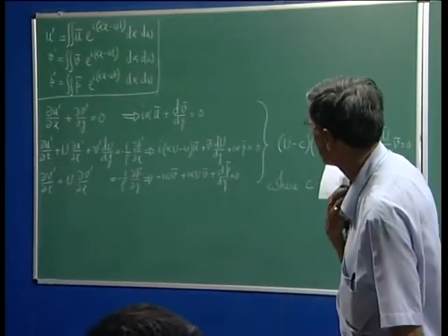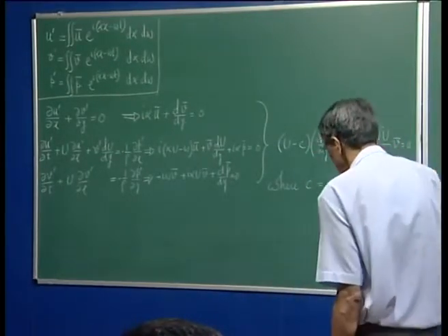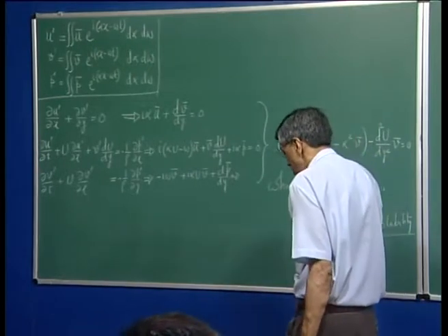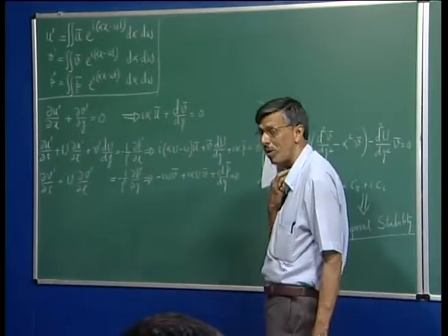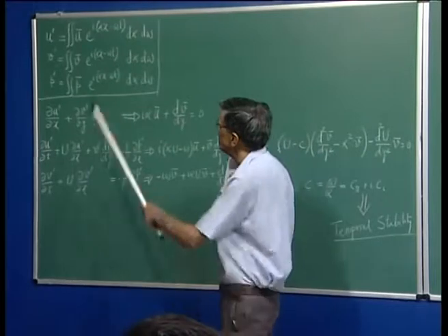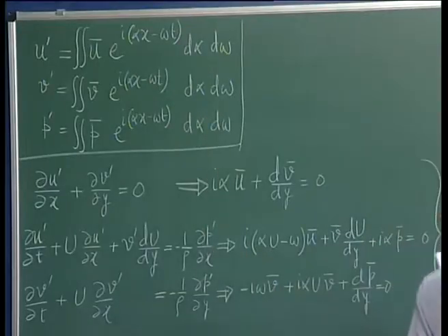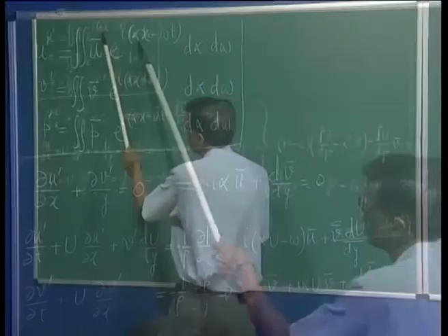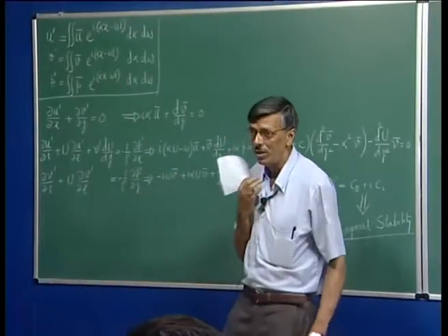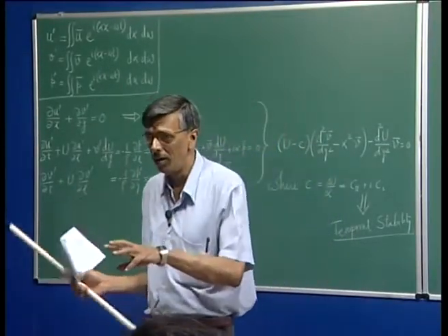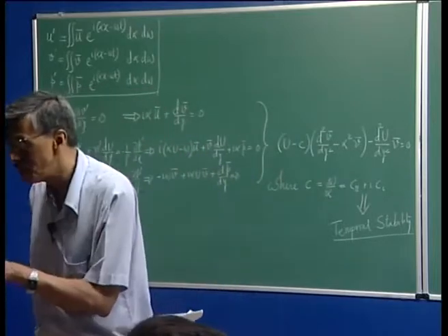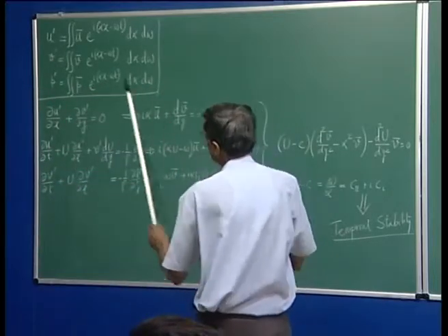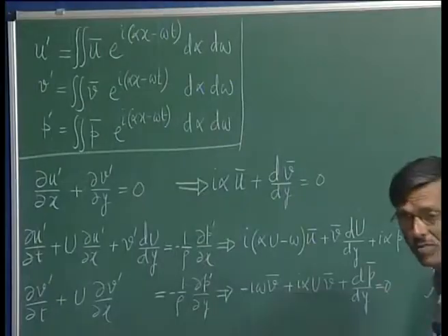Well, we said that when we are studying a stability problem, unlike the equilibrium flow problem, we must have the liberty to keep them complex. If we keep them complex, then what happens? Alpha being complex means what? The real part of alpha will give us a phase, e to the power i, so this will be a phase definition.